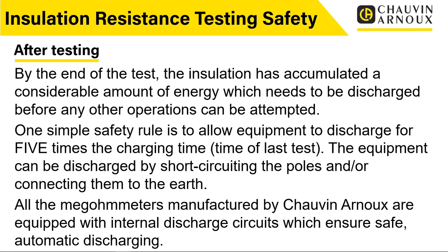So again, think about that. If you are moving from point to point to point, you may need to manually discharge them, or use a test lead or something to discharge those parts after the test. It's also important to leave the tester connected for a period of time after you've stopped the test to allow that discharge to take place. So just be aware of those things. It's an important safety precaution that often gets missed.